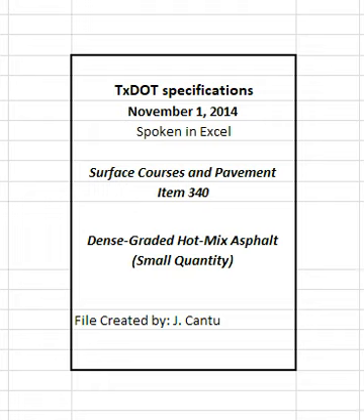Surface, intermediate, and base mixes referenced in Tables 4 and 5 are defined as follows. Surface. The final HMA lift placed at or near the top of the pavement structure. Intermediate. Mixtures placed below an HMA surface mix and less than or equal to 8.0 inches from the riding surface, and base. Mixtures placed greater than 8.0 inches from the riding surface.